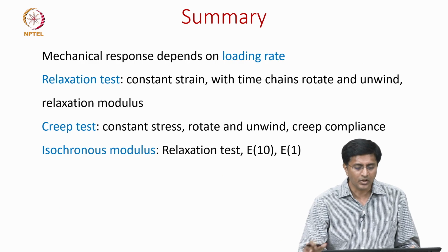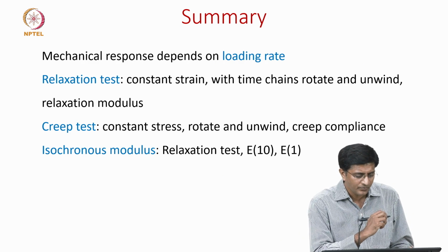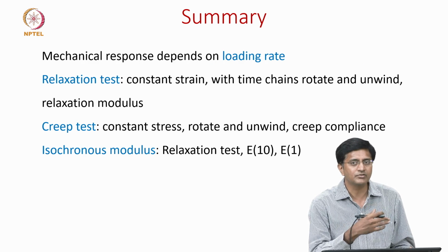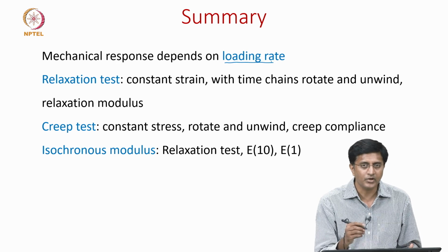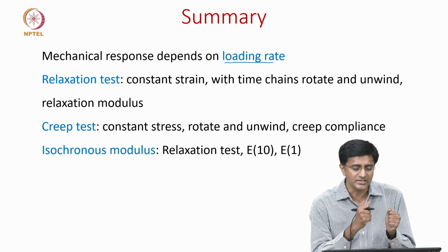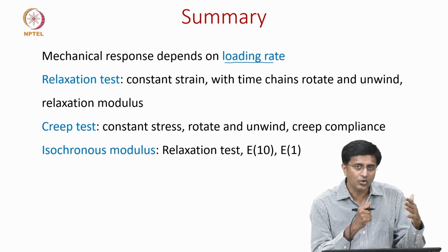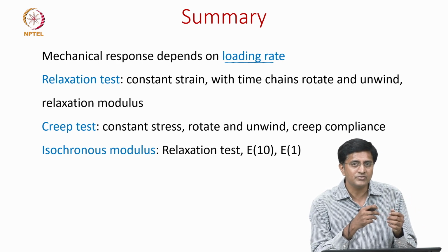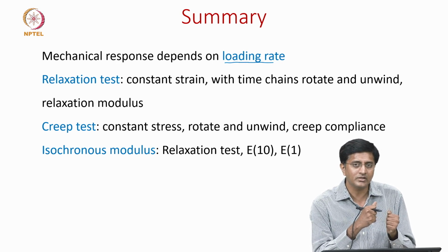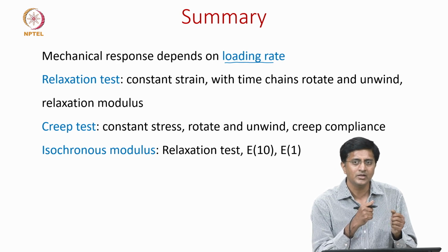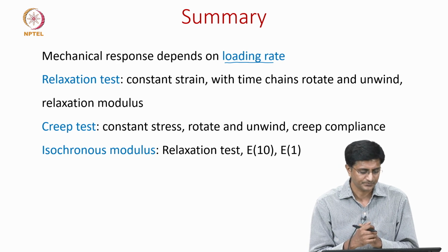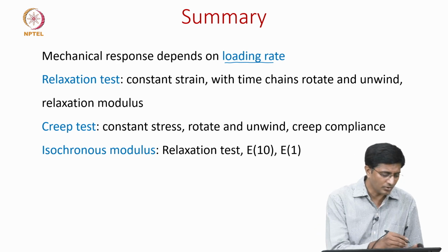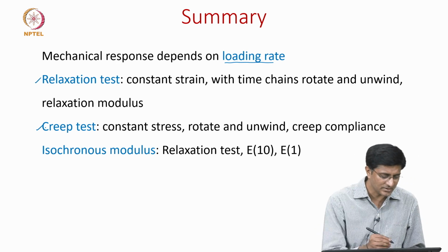Now, let us summarize what we have discussed in this video. We were discussing the time effects of the polymers. We started by saying that loading rate is very important when we design or plan a test. With PVC we have seen that brittle behavior is shown when the loading rate is very high, but when the loading rate is low, then we see a ductile behavior. Then we also discussed 2 important tests, which are the relaxation and creep tests.